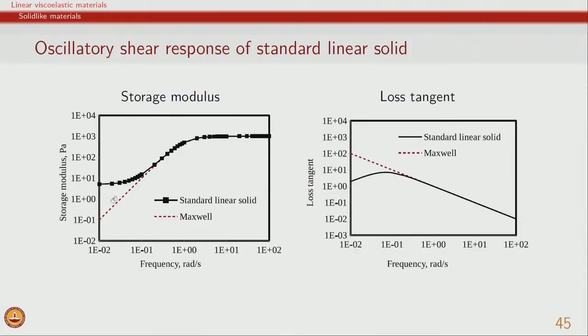One shows the solid-like response where G prime is independent of frequency, the other one shows G prime which is proportional to omega squared. Of course, since both of these are simplistic models, with the help of one relaxation time both of them show the transition to a glassy state. Most real materials will have a set of relaxation processes, and therefore, the overall transition to a glassy state may be over many more orders of magnitude of frequency, instead of 1 or 2 orders of magnitude, as seen in a simple Maxwell or a simple standard linear solid model.